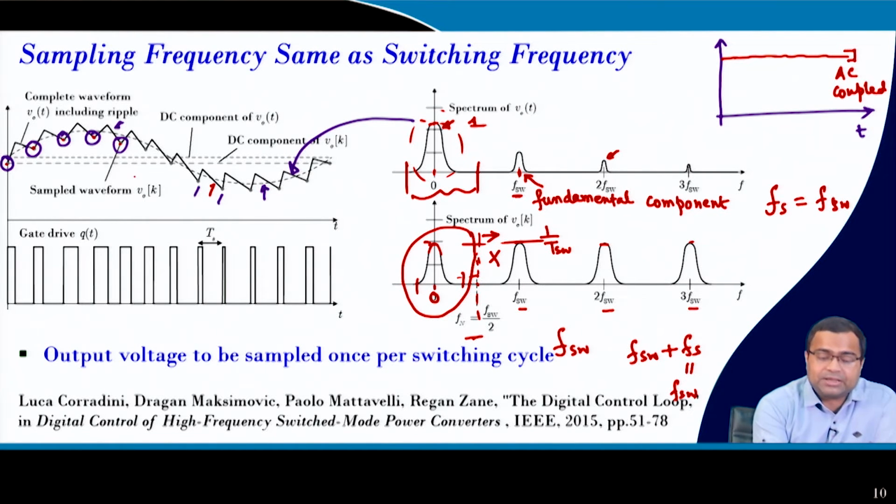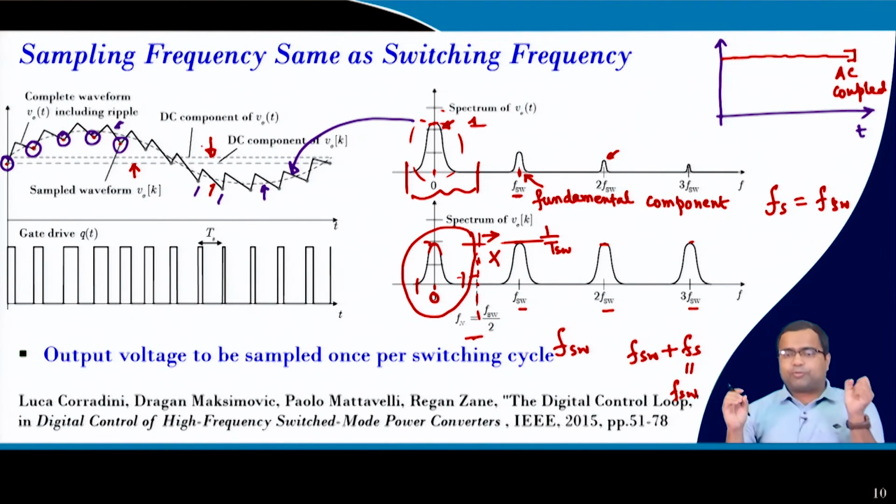As a result, your sample voltage is here and the actual average voltage of the DC converter is here. So, you lose some regulation, and you have to anticipate that by suitably providing an offset to the reference voltage, so that it can be taken care of.